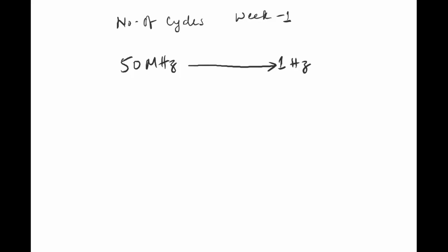All right. So is everyone clear so far? Is everyone okay with this 50 megahertz to 1 hertz logic that we are trying to implement? I had a quick question about it. There's also a 10 megahertz clock in there. Can we use any of the clocks that are present? I'm pretty sure the default clock is 50 megahertz, but if you are able to generate a 10 megahertz clock, you can always use that. But again, you need to do different calculations to make the conversions. We'll get to the calculations now. Cool, thank you. All right. So is this clear for everyone?